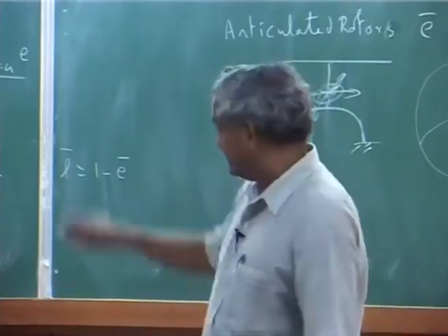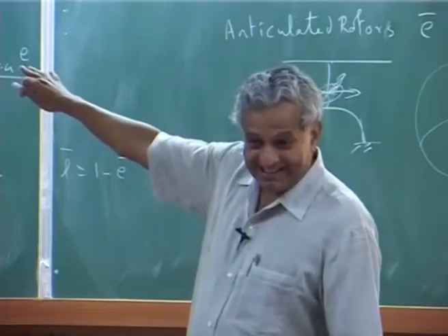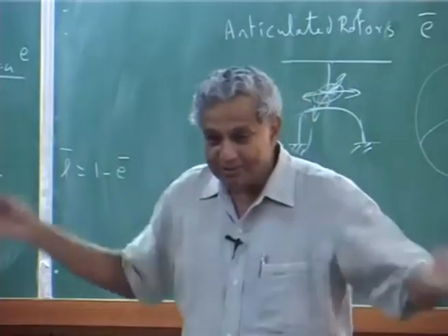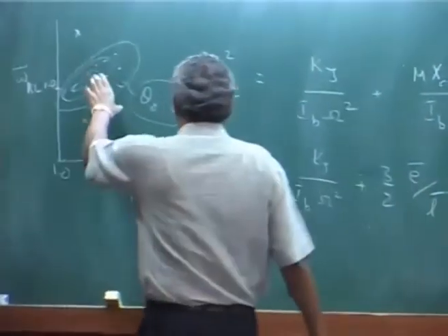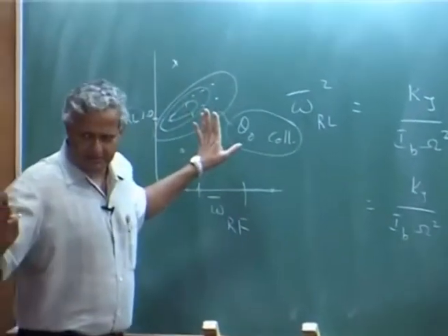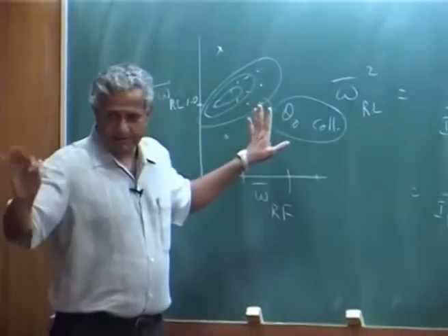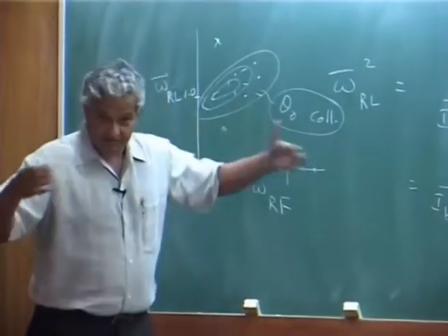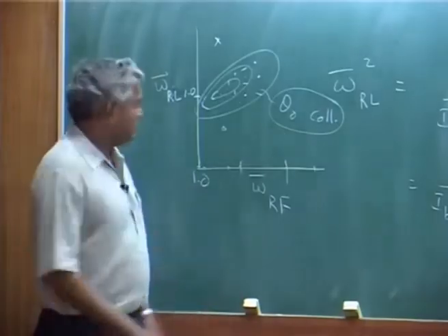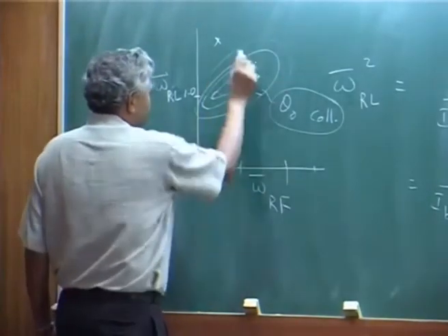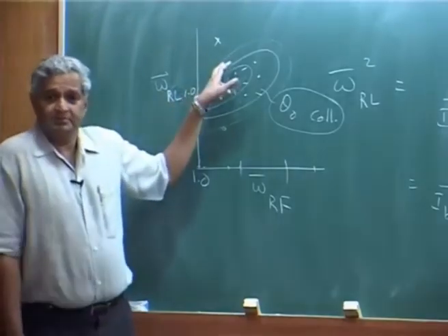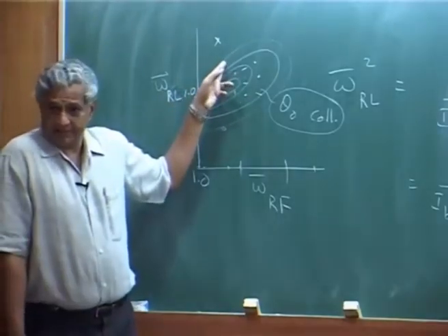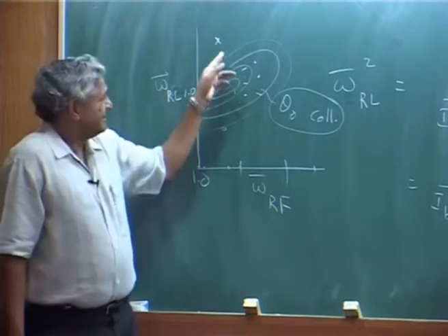Make sure that you are away from the bubble and your pitch angle is never going to hit that. See, this bubble will keep on expanding, of course, this is based on very simple calculation, not with stall model and other things. But if you use a more systematic analysis, the bubble may become like this for another pitch angle. But if you know that you are never going to operate at this angle of attack or pitch angle of the blade, it is fine, okay.